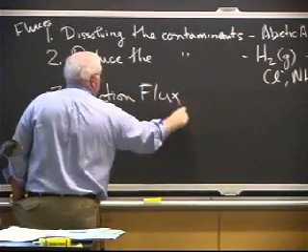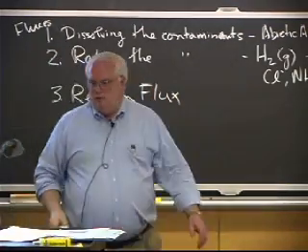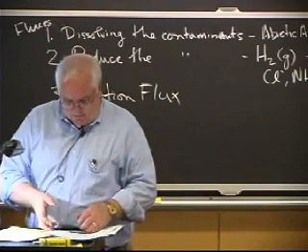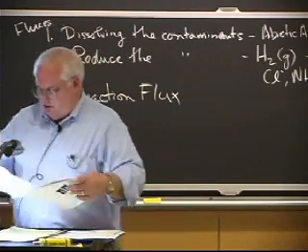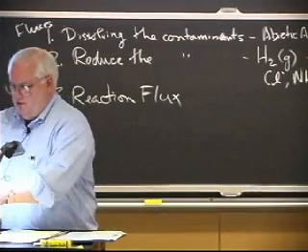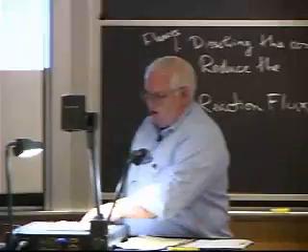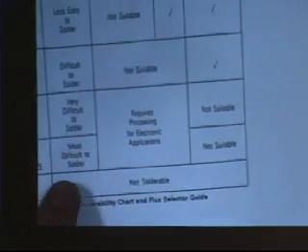And if you look at the little table that's in your handout that I put up yesterday, it talks about aluminum requires pre-coating for electronic applications and soldering. It says very difficult, or most difficult to solder is aluminum. Oops, I better zoom this down. Okay, but the aluminum and aluminum bronze, it basically says the most difficult to solder.